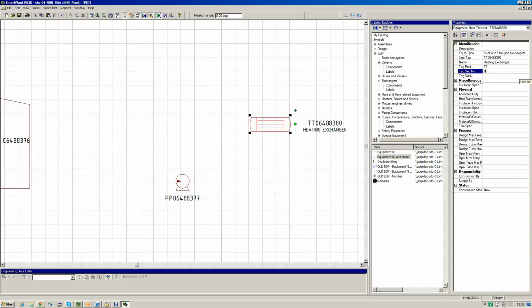We can call it 01 if we like. And in this case there's a unit number and the name of the equipment type, which we have called tag prefix. So the tag prefix, the sequence number, the suffix and the unit number together make the item tag in this case. It could be configured in different ways, but this is how it's done here.